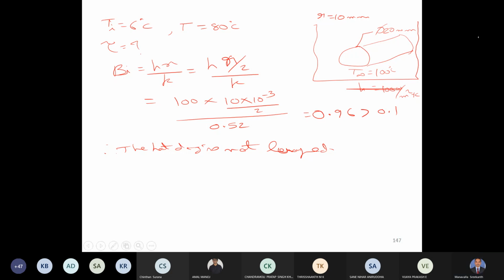So this is the center line, and whatever this graph gives are the values on this center line. Temperature is on the y-axis, Fourier number on the x-axis. Remember, Fourier number is a non-dimensional way of representing time.